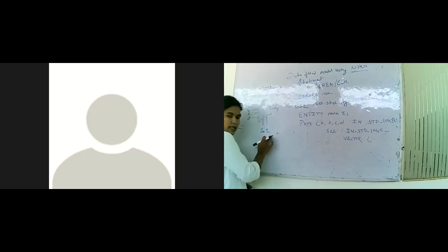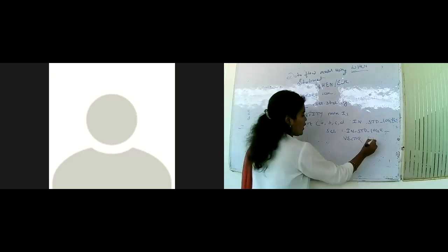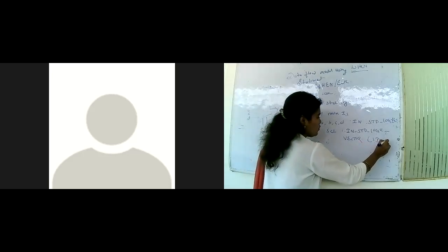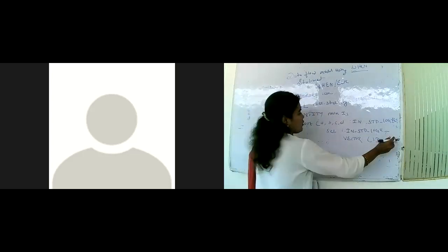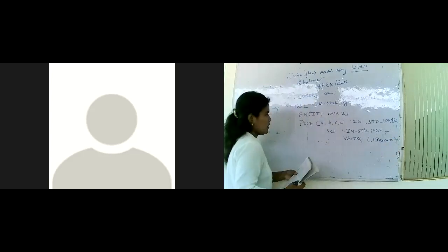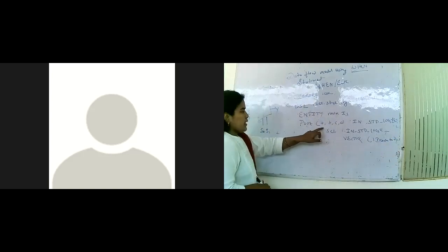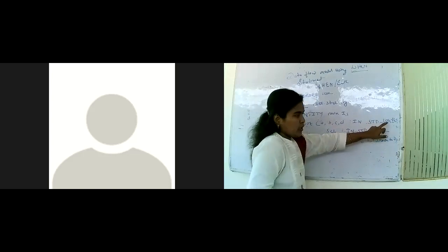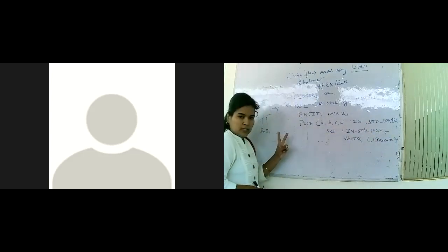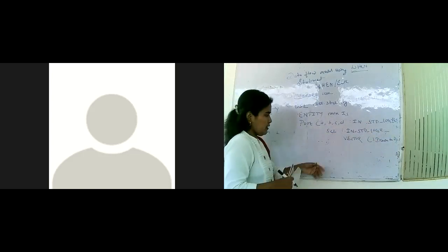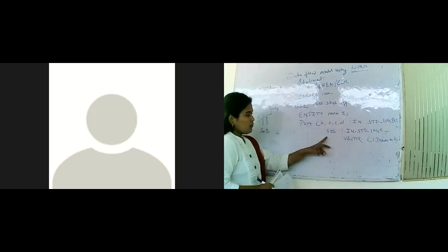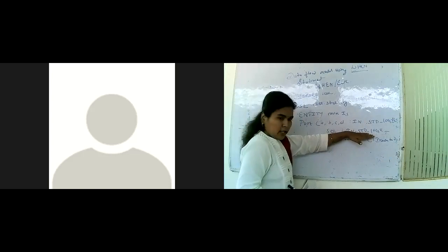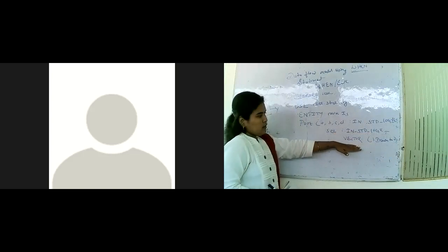So I am having here S1 and S0, so what will I write? 1 down to 0. What is the meaning of this? I am having four inputs A, B, C, D in std_logic. I am having two selection lines, SEL, the selection line, for which I am having std_logic_vector.